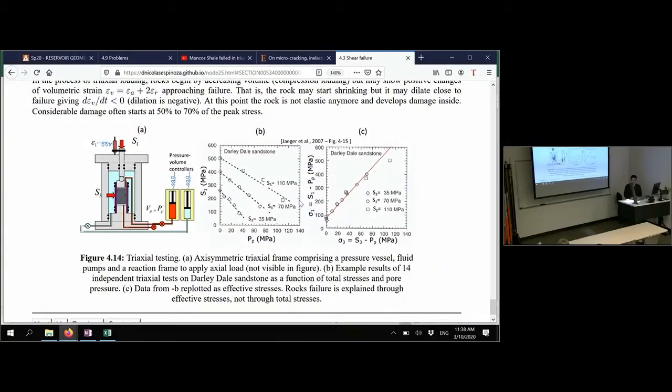to this case, where all your data should more or less line up in one trend. If it doesn't line up, something is wrong. Some points may be a little bit off, especially at very high stress, but they should more or less line up. Once you get that, trace a line. The slope is the friction coefficient Q, and the intercept is the UCS. And then you can use the equations that I'm going to give you, and that you have in the notes, in order to convert that to friction angle and cohesive strength.